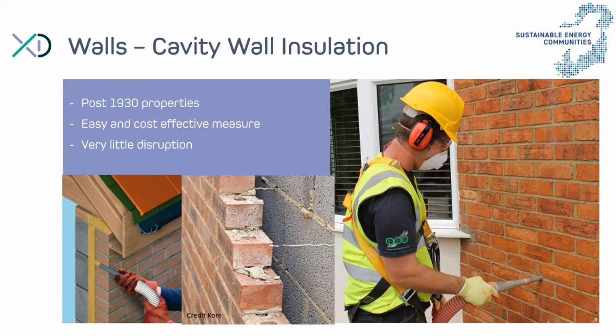typically an insulation bead with a bonding agent in the cavity and under pressure, so that you fill all the gaps wherever possible. It's very good practice before that's being done to inspect the cavity. So you can use a little camera called a borescope, I think. So you drill a small hole, you push the camera in, and that camera will let you inspect what the situation is in there, is there a material already, and to generally make a good plan for the cavity wall insulation. So it's a low-cost measure.